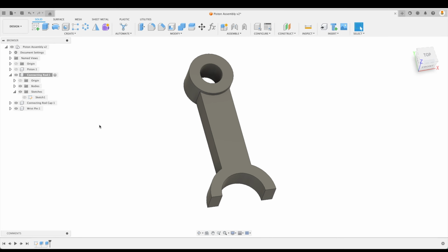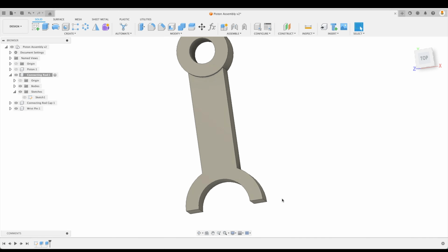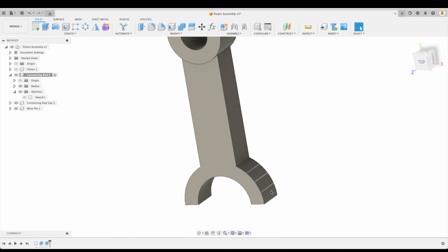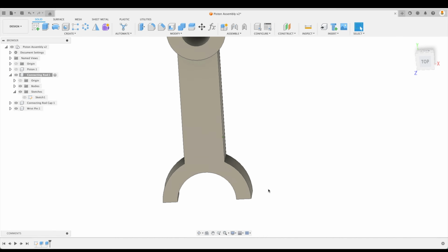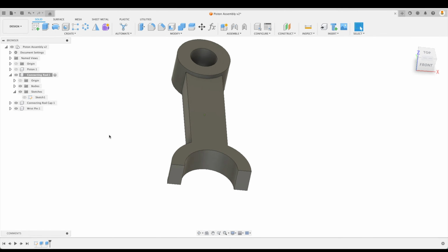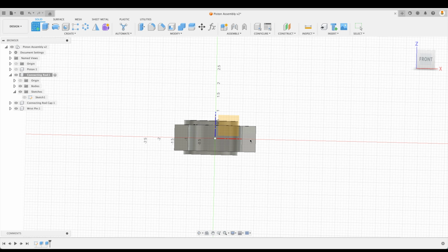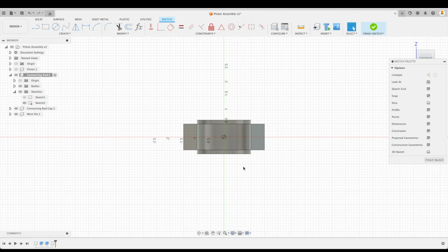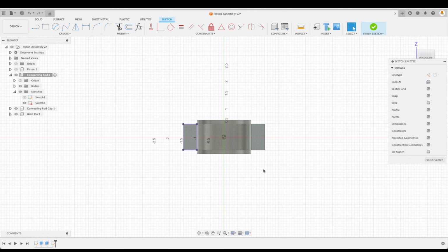So let's hide our sketch. Now before we do that, we actually have our bolt positions over here, which are going to be threaded. And we can add that right now. So let's create a sketch on the end surface there. I'm going to project this surface in. Why? Well, we've created a sketch on this surface, but it doesn't pick everything on an imaginary plane and inherit those dimensions. We actually have to project the other side in order to utilize those as well.